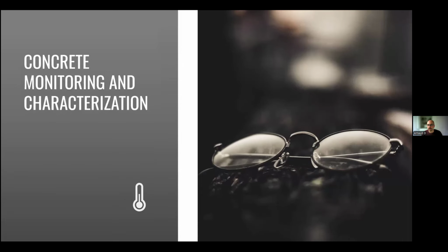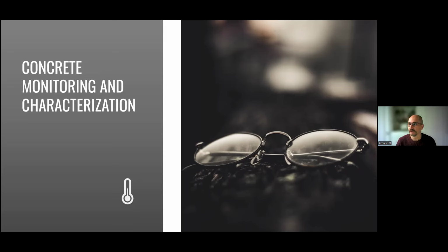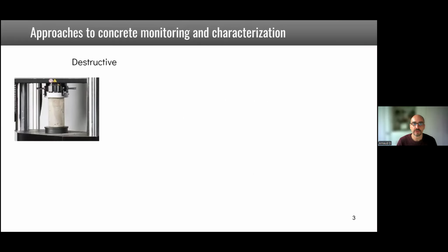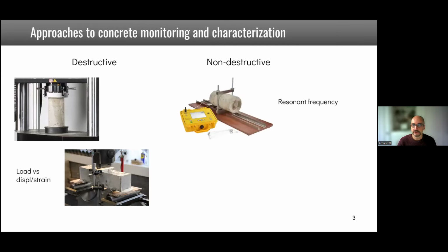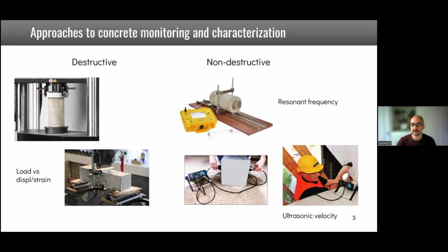For those of you who are in the network, you know that my work is on concrete monitoring and characterization, but I think we have some external guests, so I want to introduce that shortly. When you want to monitor and characterize concrete, you can do it with destructive tests, taking cores out of a structure and then testing them. You can also do it non-destructively with resonant frequency testing or ultrasonic testing. These are examples here with external probes.